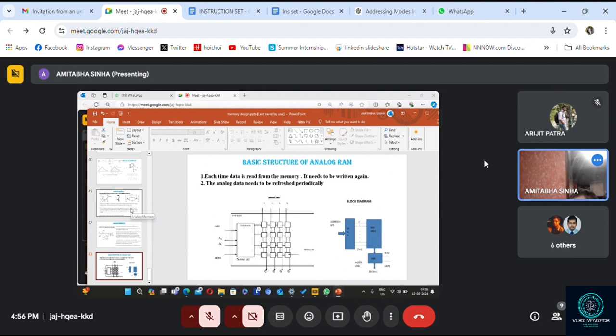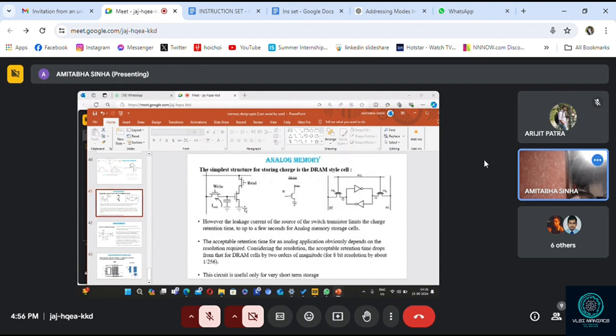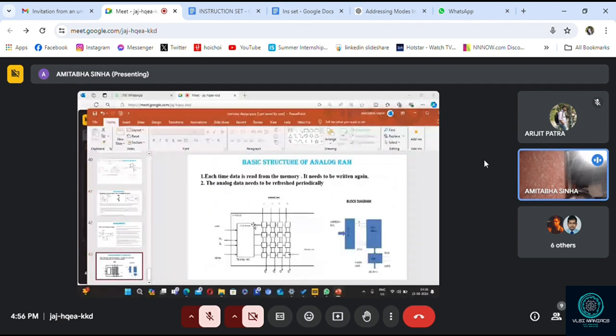This rectangular block shown here is nothing but this circuit. At the input, at the top, I1 is there. I2, I3, I4 will not be there, only one input, I1. Before I1, there is a sample and hold circuit, only one, because at a time only one sample will be stored. Then where will it be stored? Depending on which row is selected.